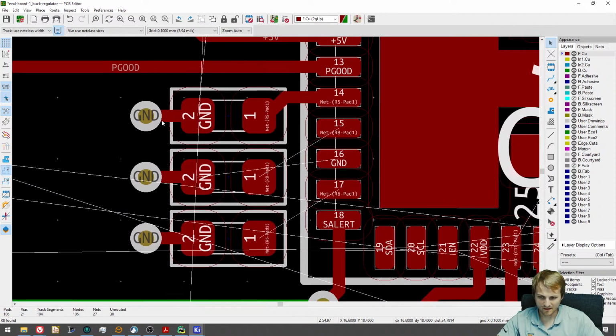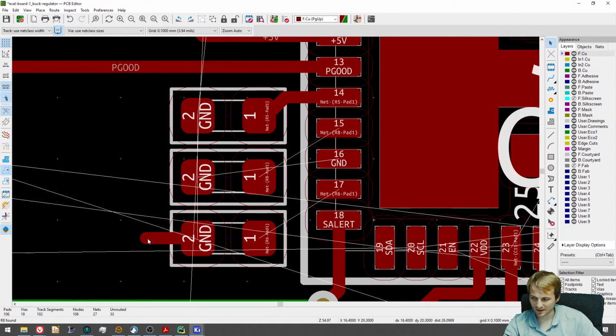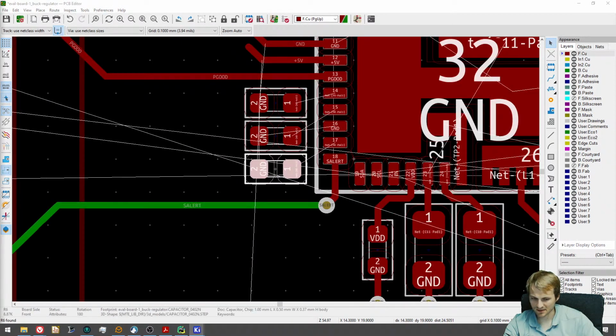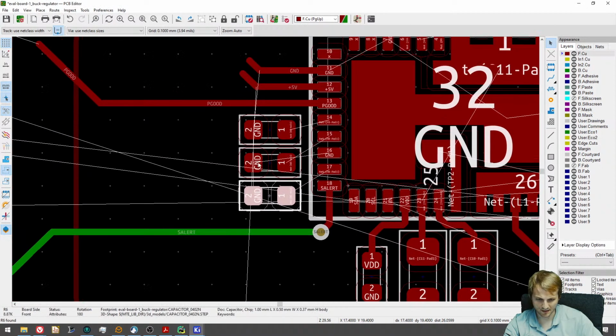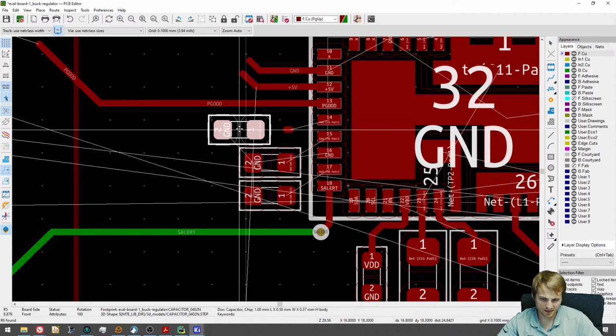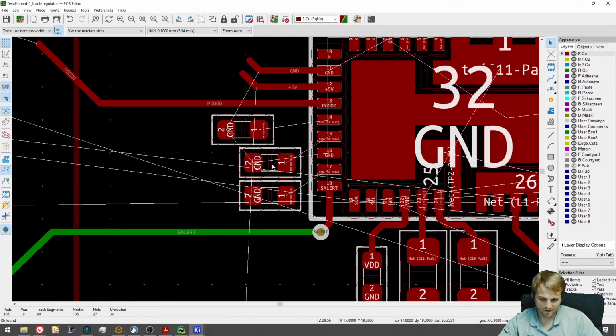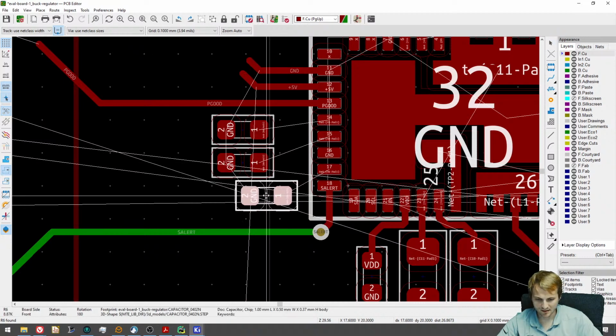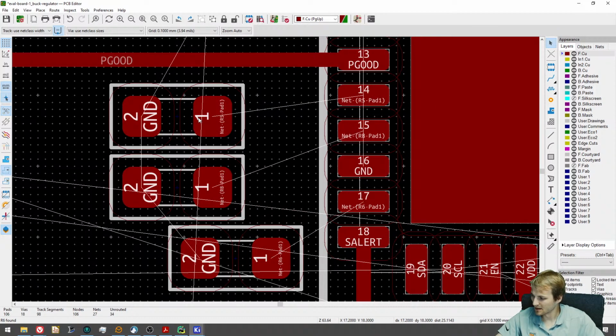Okay, these will move out a little bit. The only one that really matters being close is the RT sync pin, which is the bottom. So maybe we'll move these out a little and then try to keep the sync a little bit closer.